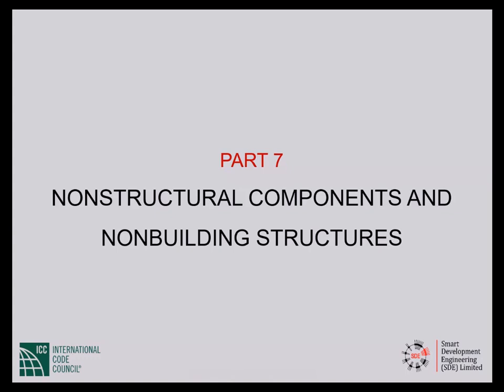I do not know what needs to be explained. If it is a roof member not supporting a plaster ceiling, then we can tolerate more vertical deflection. That's all that the table is trying to tell you.